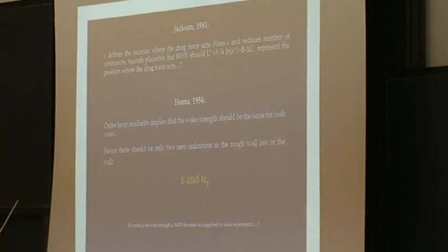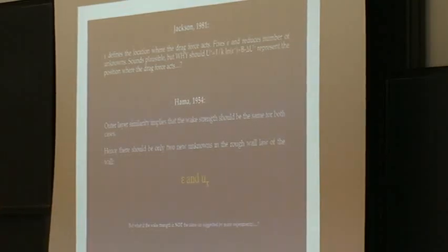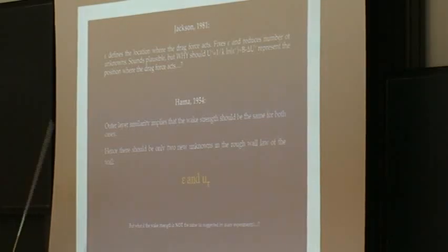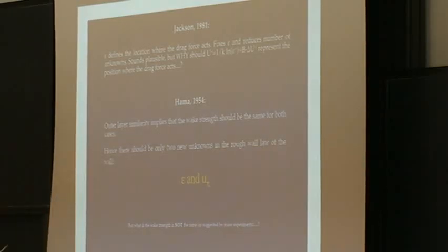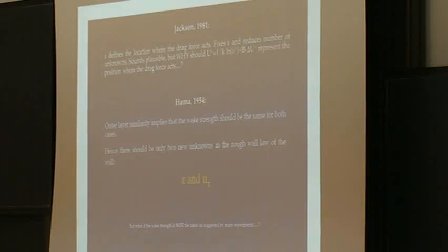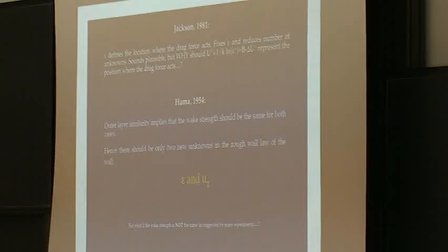In the early works on rough surfaces, a lot of people used a statement by Hama, who did rough wall measurements back in 1954. He said that if Townsend's hypothesis applies, it must mean that the wake strength is the same for rough and smooth walls. And so if you do that, then you will fix another parameter in your fitting procedure.